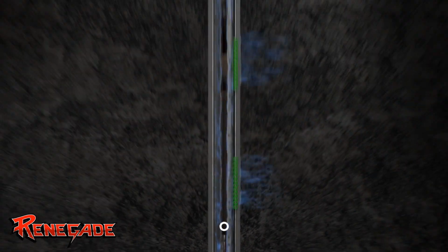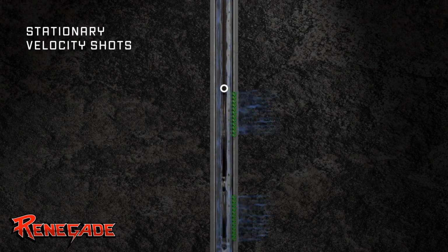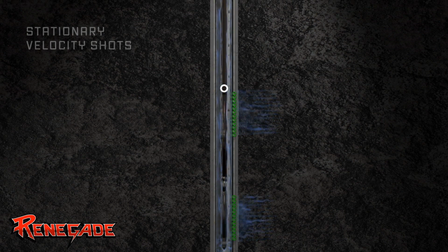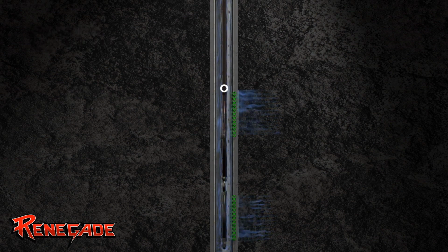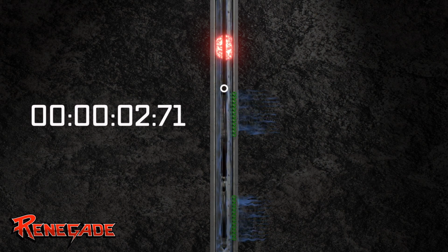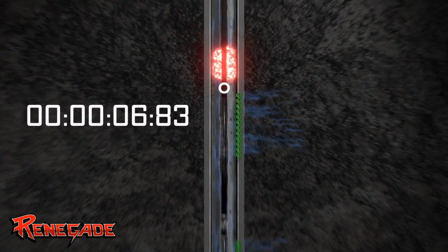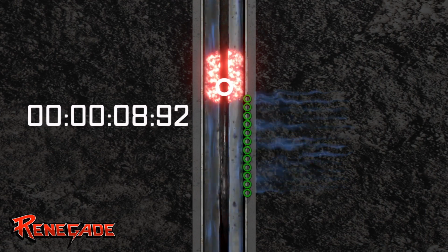We then shoot stationary velocity shots every 10 foot through zones of fluid losses to break down the losses into smaller intervals. We keep the tools still this time and fire a small slug and time how long it took to go from our ejector port to the detector. We then check for upward channeling fluid.